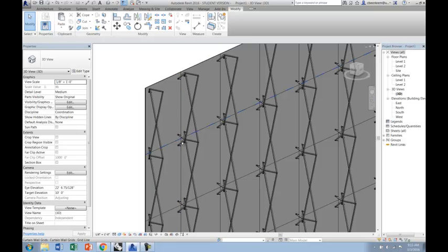I'm going to let you guys finish some of the components without necessarily going through all of them. I think you'll get the gist once we've gone through a few things. A key aspect to maintain throughout the composition is that you have to ensure that every single object you place has reference planes and is locked to reference planes that are either part of the reference for how they go into another object, or that are locked to the existing reference planes that'll come in. Hopefully that'll make more sense.